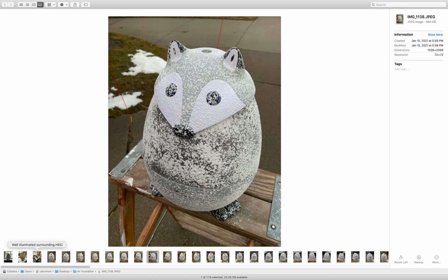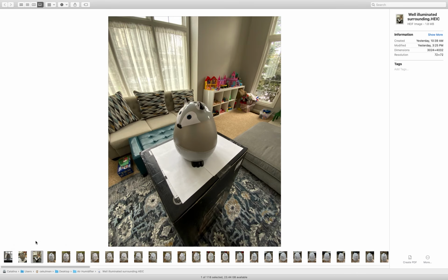Illumination is also very important. You see here in this case I did this in the evening time of the day, so harsh sunlight is not very good. The best situation is morning or evening, ideally when we have an overcast, because this is a nice soft light box then. We also don't want to have any sharp or harsh shadows on the object, because the software could read these shadows as part of the three-dimensional geometry. If you cannot take photos outside, we can still do something in the inside.